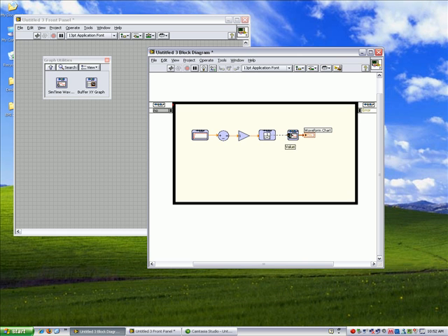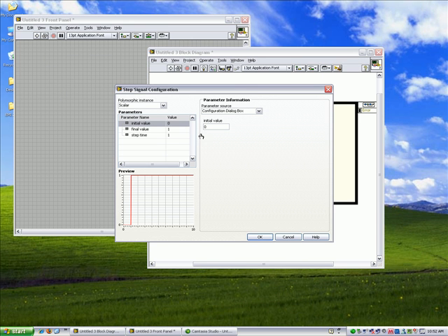So let's wire this up. Let me close my looping here. And I'm going to set up the different blocks. So I'm going to double click here. Well, in this case, I'm going to leave everything as default. So initial time is 0, final value is 1, step time, or the time where we're going to see the change, is going to be 1, and you can see the preview in here.